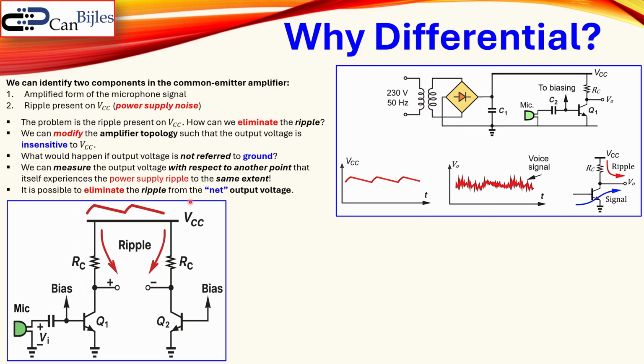And I have now here mirrored, this is the differential operation actually. And you see here the ripple of this VCC again, and that ripple will be again going to this node and also to that node. So this is the exact same ripple. So what happens here? Well, if we now designate this output voltage VO1, that's the node, and another one is here VO2, the difference between them is our differential mode output, which is then our VOD. Now VOD is VO1 minus VO2.